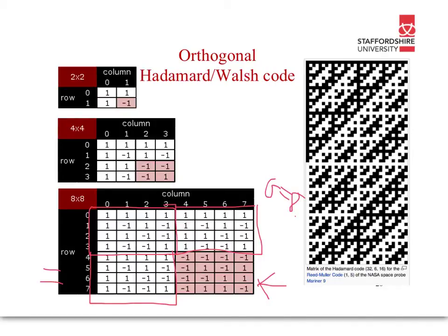The problem with this is we've got a fixed spreading gain. So for true orthogonality, for example, we couldn't give this as a spreading gain. If we gave the code here for a spreading gain of 4 for one user, those spreading gains are the same. So this is a subset of this. They're all subsets of each other, so these are not very practical. If we've only got a small number of users, then these are very secure. However, they're not practical.